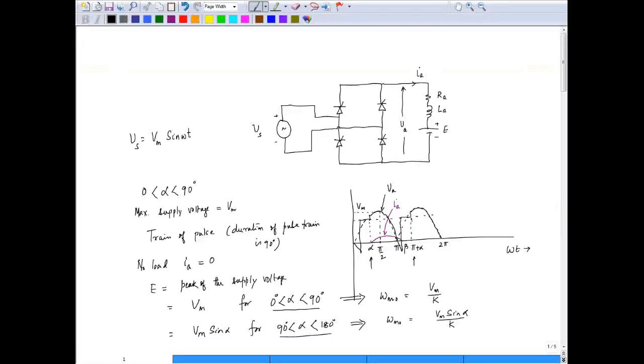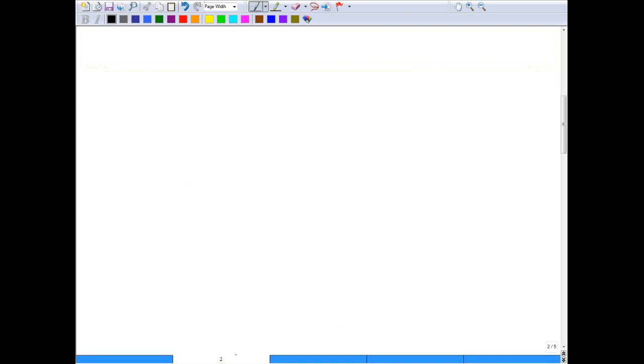Okay. I want to know about the torque ripple of a low-cost unipolar BLDC motor. It is thrice the rotational frequency. Now, if you see the low-cost BLDC motor, let's see why the ripple frequency is what it is. We have the windings, which you can see in the lecture notes. Delta varies between 120 to 0 degree.